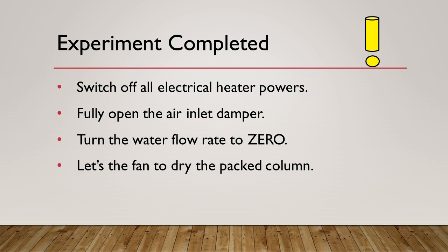When the experiment is completed, please switch off all electrical heater powers, fully open the air inlet damper, turn the water flow rate to 0 and let the fan dry the packed column.